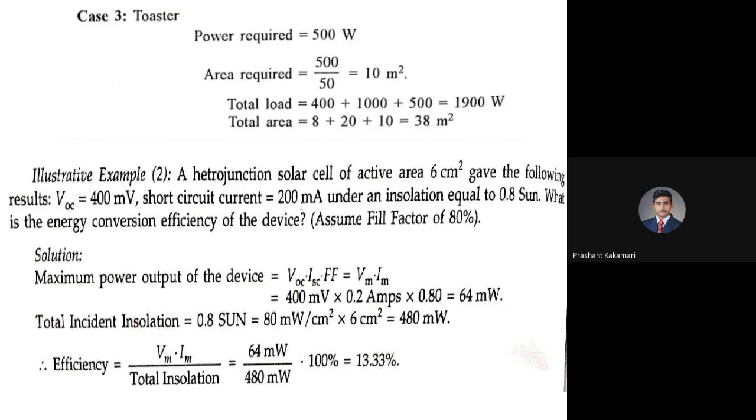So like this, for given applications, knowing the efficiency of the PV cells and the solar radiation possible per day or per given time, one can find out, for the number of bulbs, appliances or different devices to run in the home, what the total load is, and what the total area required to implement this solar system is. If that area is available for the building, you can go for that. Or else, you might have heard that only for lighting we have taken the solar system, and to run the remaining appliances we are using the grid connection power.